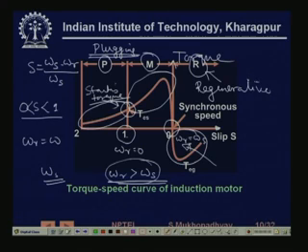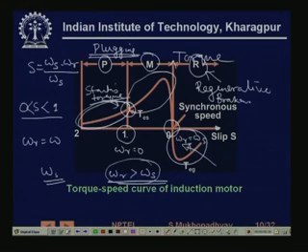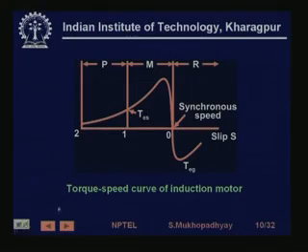During this phase, if you allow current to reverse, then the motor mechanical energy will be fed back to the electrical source and will be converted to electrical energy. So, while in plugging, the mechanical energy will be dissipated as heat and will result in high temperature of the rotor. In this case, that will not happen, but the power will be fed back and the power will be saved. So, this is the regenerative braking mode. So, these are the main modes of interest, and especially regenerative braking and motoring are the zones of interest, right.